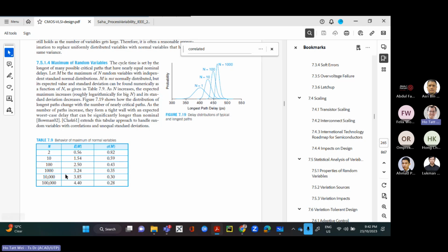And this is where we actually start to worry. We say that the critical path alone is not enough. If we have a lot of paths that are near the critical path, by this sort of estimate we will know that just looking at the critical path is not enough. We will have a new statistic or new distribution taking into account all these near critical paths, which will lead to longer delay, right?